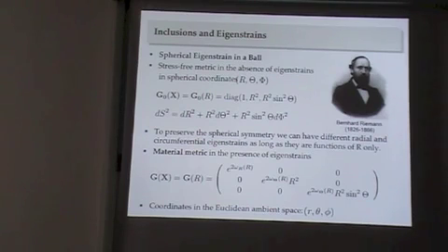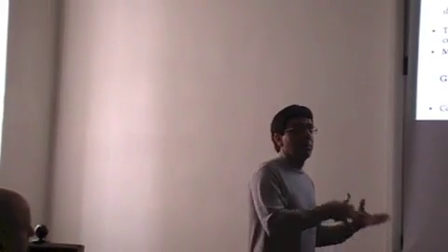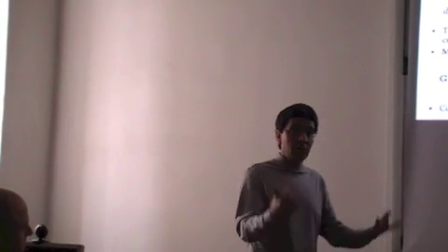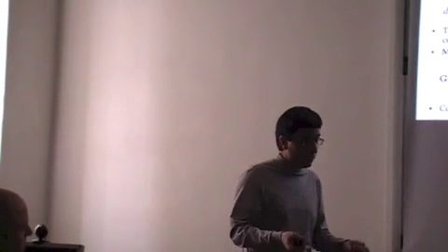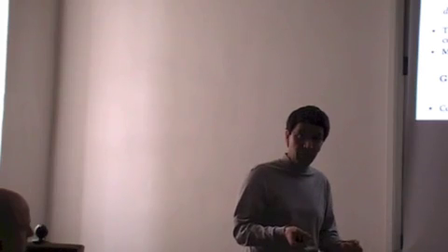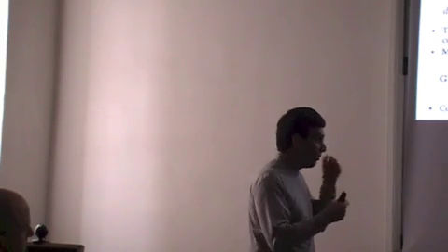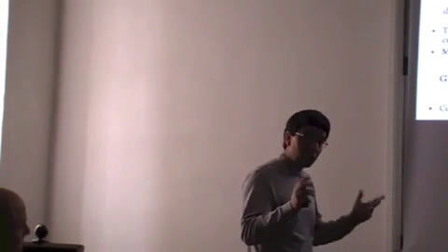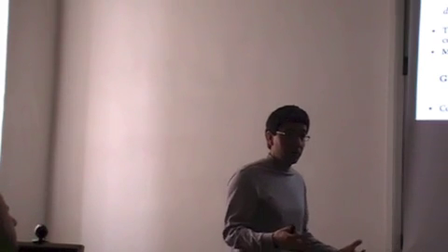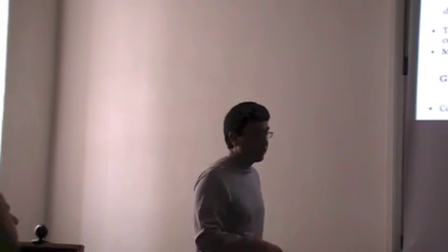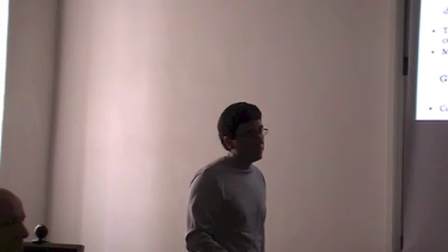So given my eigenstrains in this Riemannian manifold, it is stress free. The problem is that the moment I put this body in Euclidean space, I induce residual stresses. And that is what I'm going to calculate. See, this framework is so natural that such a hard problem you can solve. Because your deformation energy will depend on this.